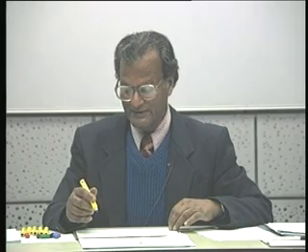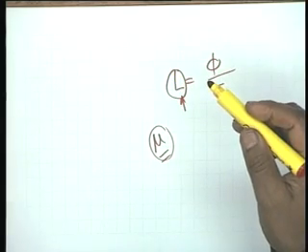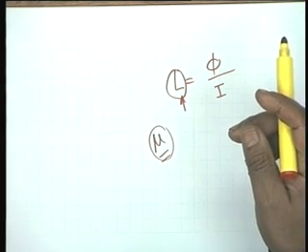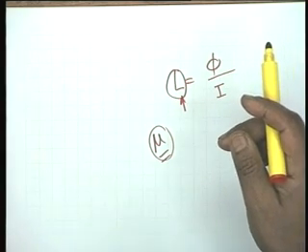In integrated circuits, the space is at a premium. All right. The other thing that you can do is to make mu high, that is the permeability high. Now, the highest permeability that is attainable is limited. You cannot make it infinite. And therefore, the value of inductance that you can obtain in an integrated circuit is typically of the order of picohenries, 10 to the minus 12, or even less, which are useless.